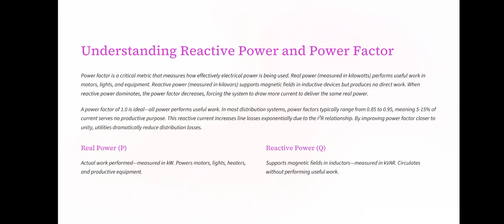Understanding reactive power and power factor. Power factor is a critical metric that measures how efficiently electrical power is being used. Real power, measured in kilowatts, performs useful work in motors, lights and equipment. Reactive power, measured in kVAr, supports the magnetic field in inductive devices but produces no direct work. When reactive power dominates, the power factor decreases, forcing the system to draw more current to deliver the same real power. A power factor of 1.0 is ideal: all power performs useful work.